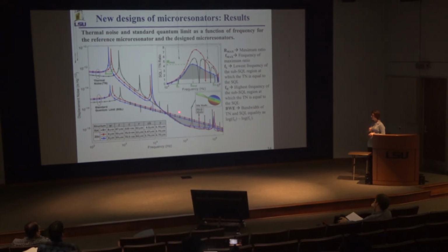So you can see, for example, in the black one, we want this fundamental mode to be between 100 Hz and 1 kHz. If it is below 100 Hz, the structure will be very fragile. If it is above 1 kHz, the thermal noise is a lot.